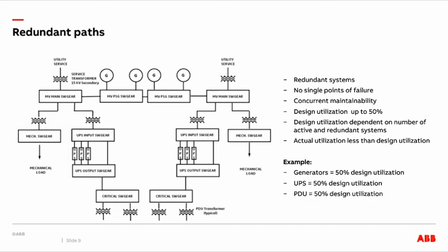Note the two-end system can support single-corded IT loads if these loads are fed from a static transfer switch or STS. In this case, the IT power supply and the STS become single points of failure. So typically dual-corded loads are recommended.